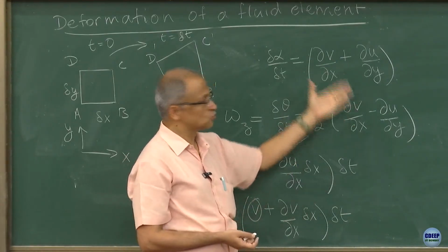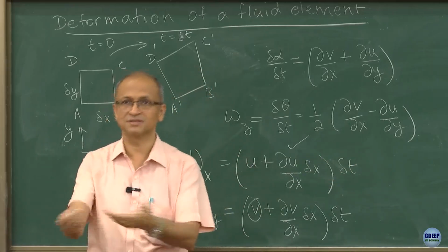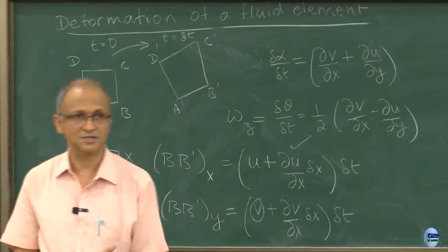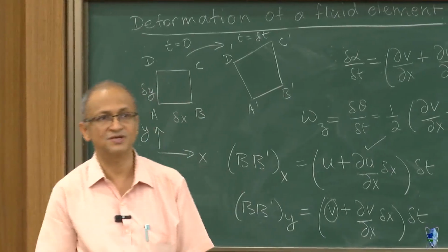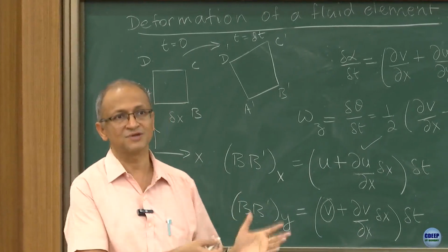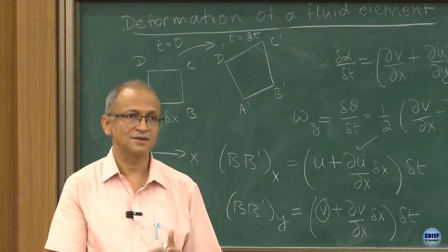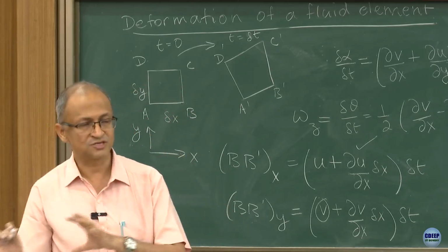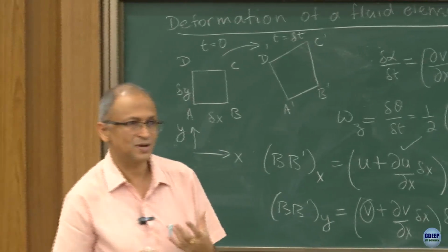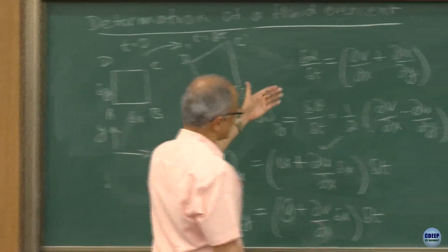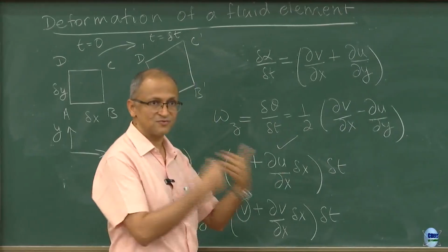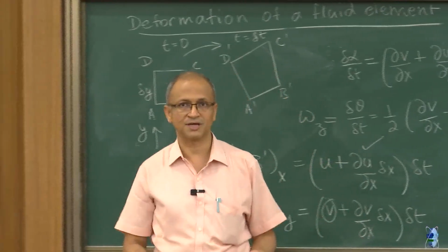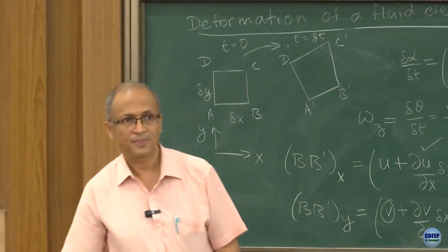Okay, so why did we do all this exercise? Sometimes we are given that this is my rotation, but we never connect it to the basic deformation or displacements of the elements. Here we can do that very clearly, very nicely, and we can see a very clear physical picture and a mathematical description of that. So that's why I like this whole derivation, because it is very transparent. It gives you very nicely, very clearly what is happening to the fluid elements.